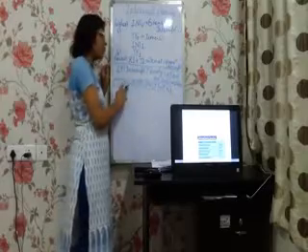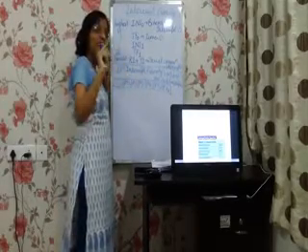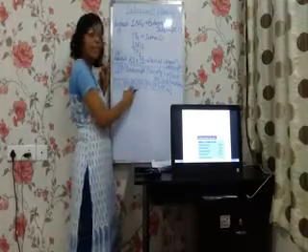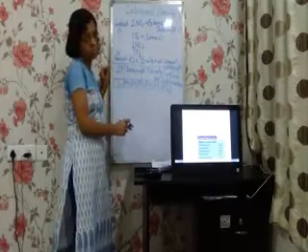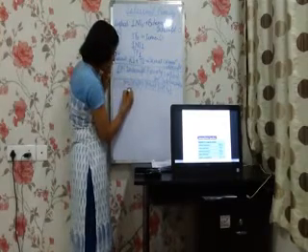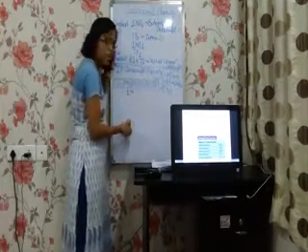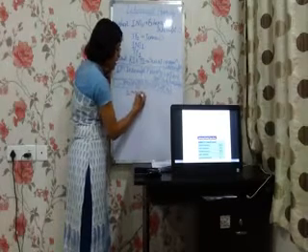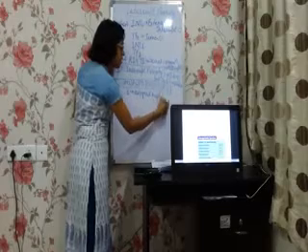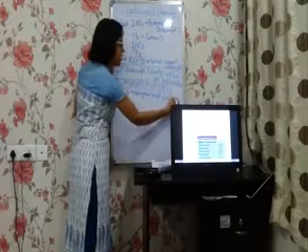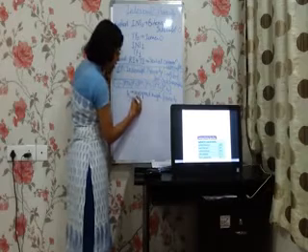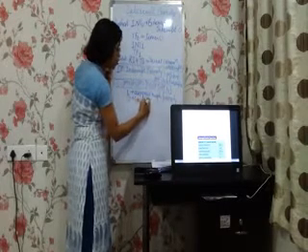There was ET2, ES, EX0, ET0. Here there is PT2, PS, PX1, PT1 and so on. So P stands for priority. If we put 1 in any of the bits, that particular interrupt is assigned high priority. If we put any bit as 0, then the interrupt is assigned low priority.